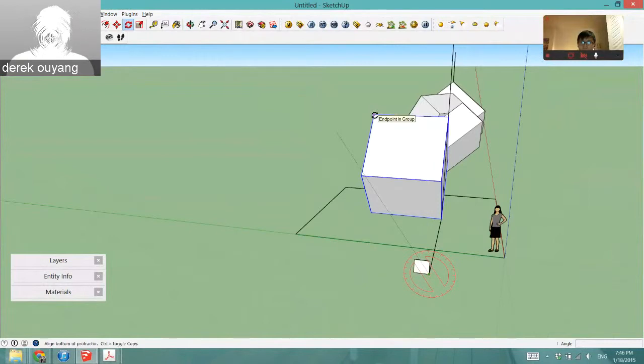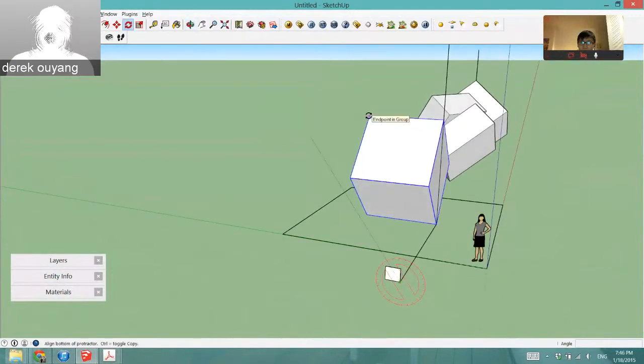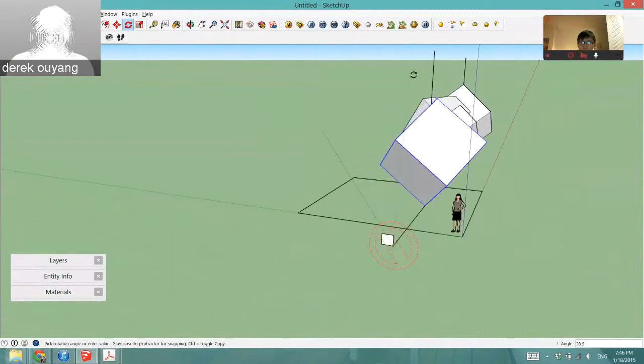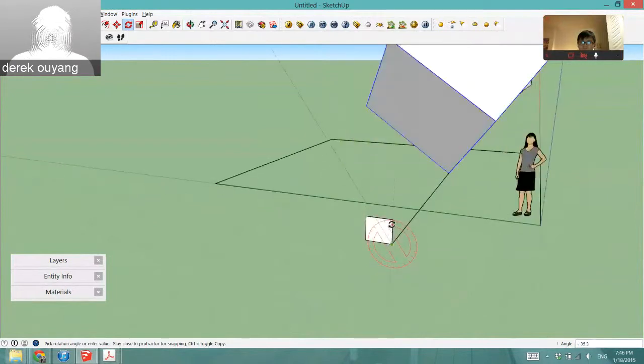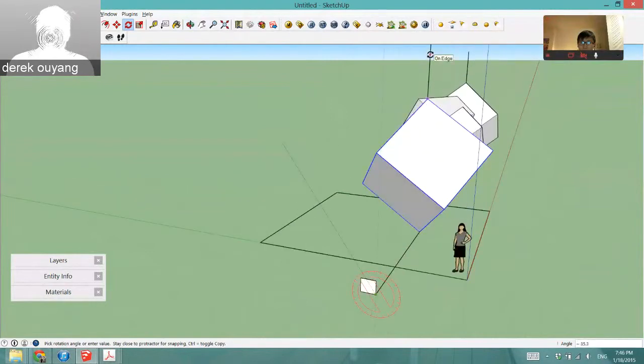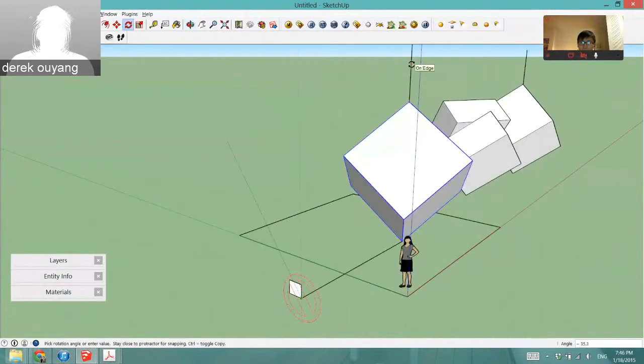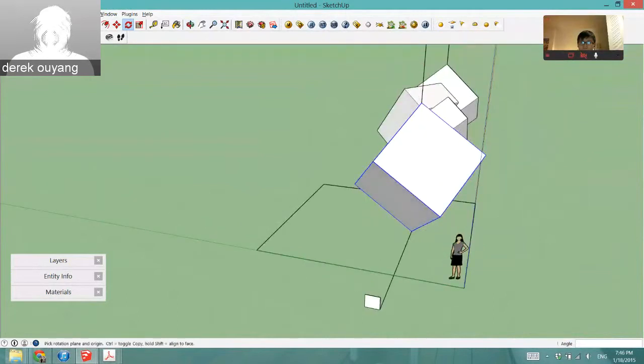And notice that even though I've hovered over the corner from what seems to be very far away from the rotation plane, it just knows what that means projected onto its own plane. So we can select this endpoint in the group, click the second time, and simply now snap onto anywhere along this line that we've created for ourselves. Of course, you could have also just snapped onto the line right here on the reference plane, but this is just sort of intuitively the easiest way to do it here. So that's just the final step you have to do there.